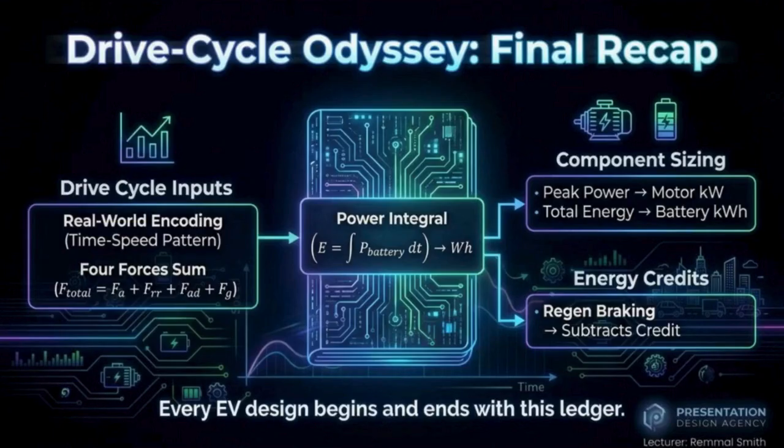Peak power determines the motor and inverter rating in kilowatts. Total energy determines battery capacity in kilowatt-hours. Regenerative braking subtracts energy credit from the total demand. In the end, every EV design begins and ends with this energy ledger. This script defines the electric vehicle as a complete system.